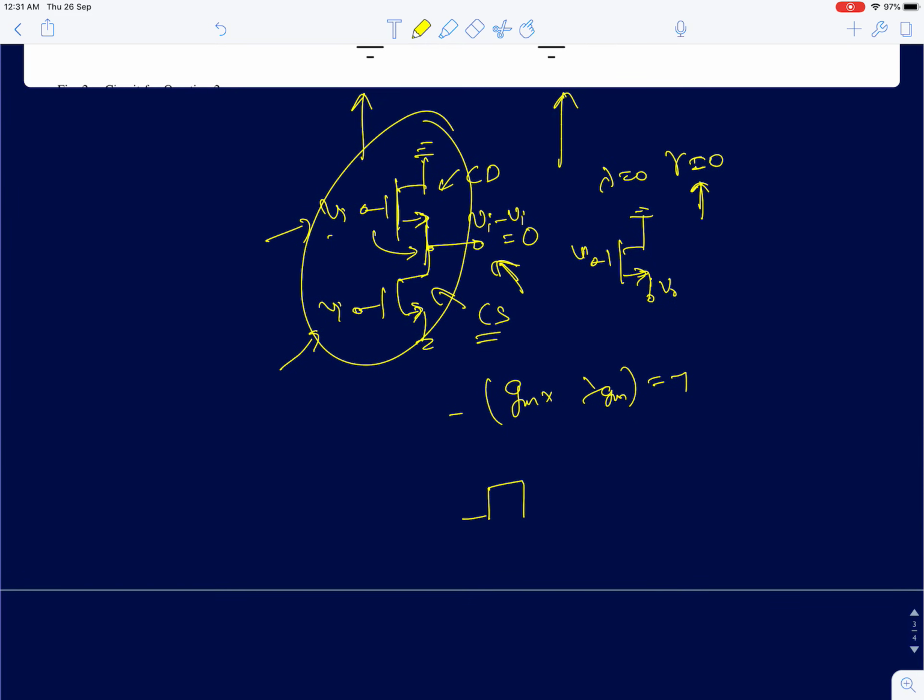So the circuit is going to look something like this. Due to VA there is no contribution. Now there is VA here. So now I'll find what is the contribution of this VA to the output. Whenever you are finding one output, we can ground all the other outputs and try finding their contribution.